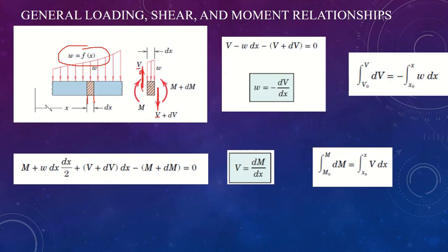We have the definition for shear force, that the sum of all forces along the y-axis should be equal to 0. So we have V minus W dx minus (V plus dV). W is load per unit length, and for the length dx we get the weight acting downwards. This whole thing is acting downwards, and the entire system becomes an equilibrium equation. If we generalize this form, V is going to cancel out with V, and what we are left with is W, that is the load distribution, is in fact minus dV by dx.